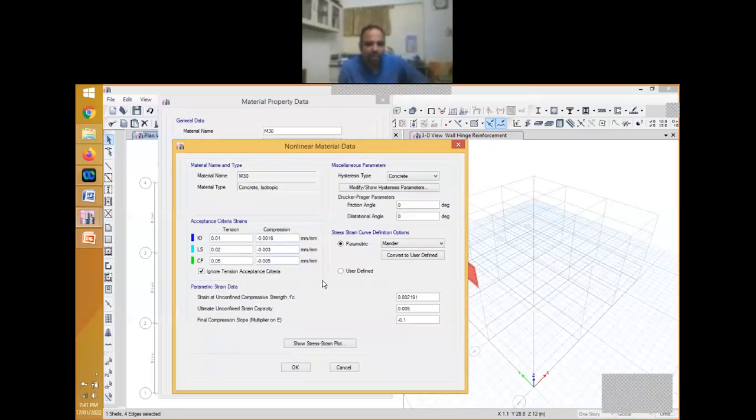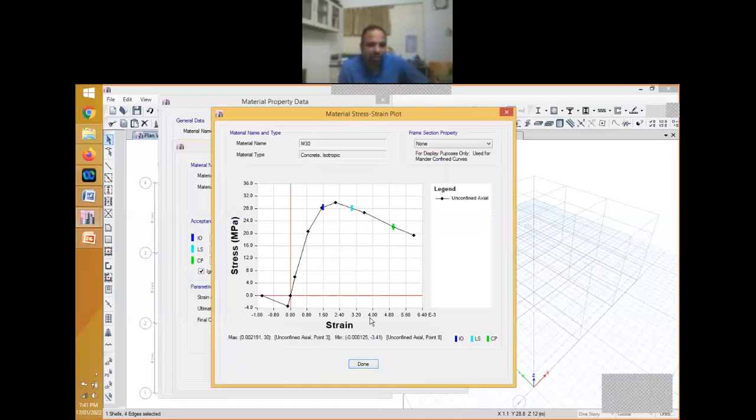Okay, so here, whatever the stress this material is using now, it is around 30. We have given it 30, so it is using 30. We don't want this program to use this 30. So it should be around 1.3 into 30. So that you change at the material level itself. So this is your preliminary nonlinear material data that you need to assign to a program.